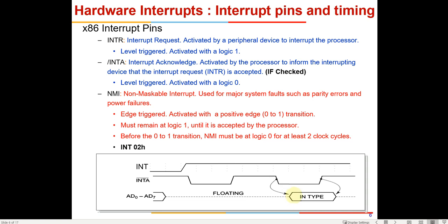The IO device will put that 1 byte of information on the data line, because it is multiplexed. So the IO puts the byte of information about which kind of interrupt it wants, and accordingly 8086 will go and execute that particular interrupt.